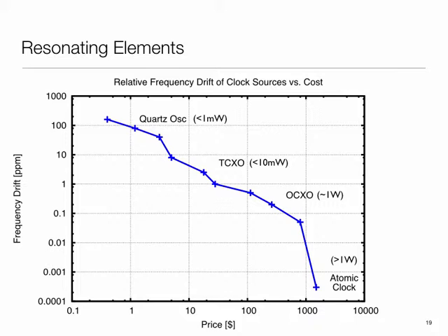By subjecting them to different temperatures, noting down their frequency against a reference frequency, and then they put that information in a little ROM inside there. So that's one approach, a digital type approach. The other is the analog approach, where you model and have a circuit which compensates for it. You pay for it in power. So you start going up in power, but you get down to 1 ppm.